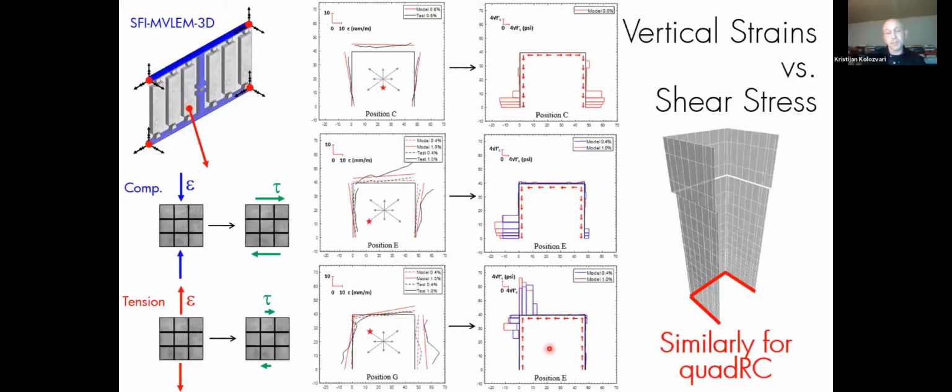models that we use currently in performance-based design can't do this. They all assume that shear is uniformly distributed along the length of the wall. There's no shear flexure interaction, right? So the demand we predict in, say, the core walls under the multi-directional loading might not be as accurate, and we're using those forces to design the building. So this will be sort of a better, improved way to predict the distribution of shear demand in the complex cross section of a wall like this.